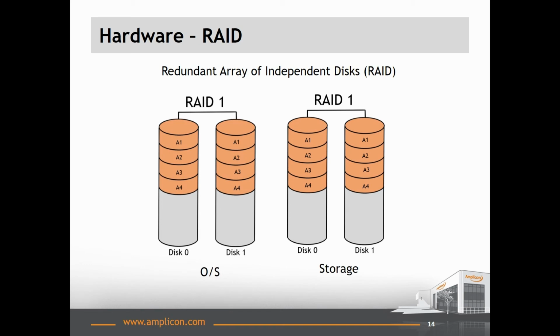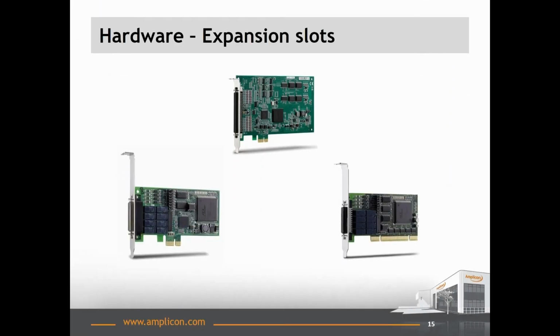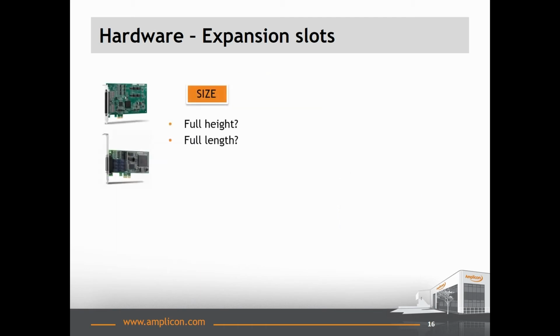Working through our system requirements, we now need to look at expansion. Expansion slots allow you to add expansion cards, be it a graphics card, serial card, or data acquisition card. The card you want to add will have a big effect on the system you need. Size, are they full height or full length? This will determine the size of the chassis you need to use.